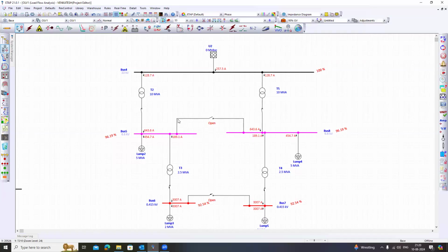Now first let's run this 95% grid voltage. Run this. If you observe here, we have run the case study for the 95% grid voltage, but still the grid voltage is 100%. If I run the 100% grid voltage, again the grid voltage is 100%. And for 105% grid voltage, which I am running, again the grid voltage is 100%, which means only by changing the naming will not really make any sense. You need to be really careful and alert about the configuration which you have done so far.